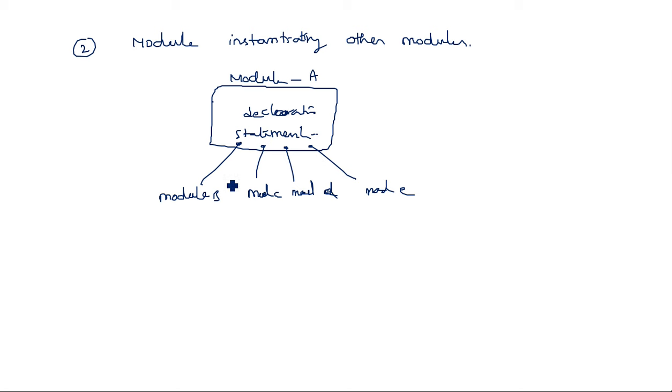By seeing this you can understand this particular module declaration is used for the structural model of Verilog coding. In VHDL coding also we have seen the structural model, where one main program is there and that program calls the individual programs. Individual component declarations are there. Whenever the component is declared, automatically the program will be connected to that particular component. Here also the same with modules. Module A is the main program. In that we are calling module B, C, D, E and so on.